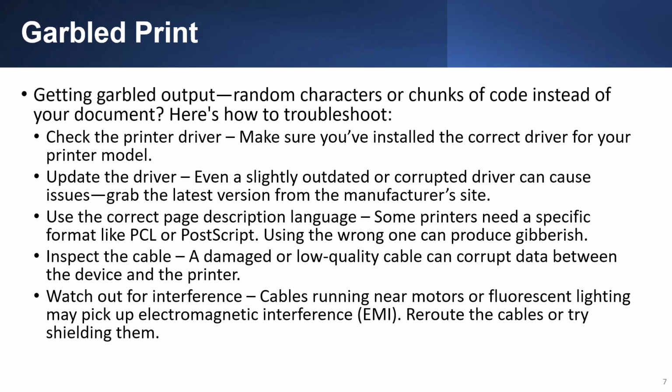Inspect the cable. A damaged or low-quality cable can corrupt data between the device and the printer. Watch out for interference. Cables running near motors or fluorescent lighting may pick up electromagnetic interference, or EMI. Reroute the cables or try shielding them.